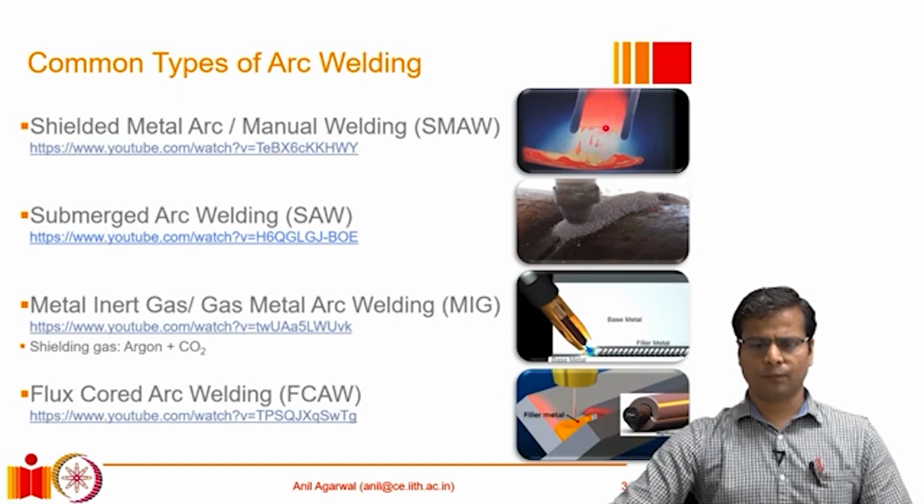As the arc continues to burn, the material gets deposited, and basically because of the forces, the flow of this material is such that it forms kind of beads or waves of welding. And there are ways to understand how good the weld quality is by looking at how regular the beads are. The beads should be very regular in order for a weld to be of a good quality. Okay. And the slag that is deposited on the surface, which is basically the consumed flux material, has to be chipped off, and then the inspection should be done on the quality of the weld.